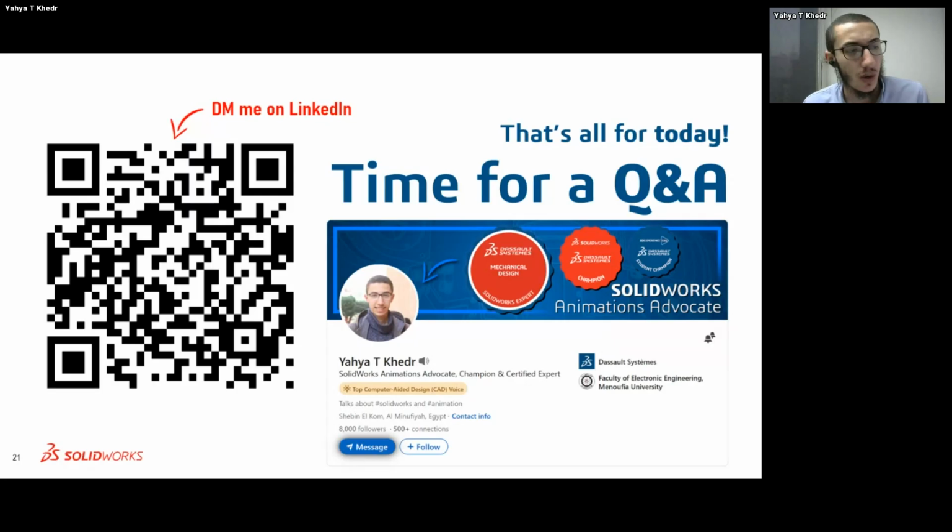It can be anything. So as you saw at the beginning of the session, when we had that 100 dimension in width, and we wanted to position the hole at the third of the width, we could do it in multiple ways. When we did it with dimensions, if we just enter 100 divided by 3, not an equation, just a value, SOLIDWORKS is going to calculate 33.33 and put the dimension. But if I change the 100, it's not going to change the 33.